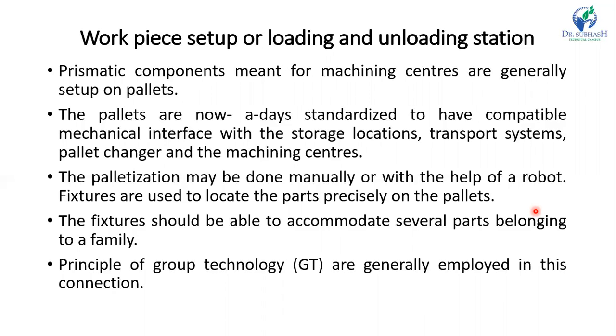The palletization may be done manually or with the help of a robot. Fixtures are used to locate the parts precisely on the pallet. The fixture should be able to accommodate several parts belonging to a family. Principles of group technology are generally employed in this connection.